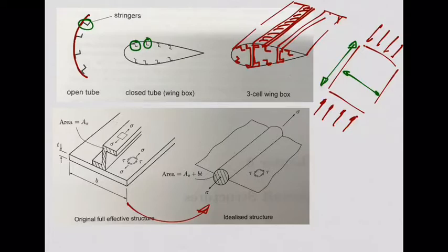Bending, you know, gives us direct stresses. Who is carrying the direct stresses? Well, that's why we have the booms here. The booms carry these direct stresses, sigma. Okay? So it's these two simplifications in geometry and in the stress states that will bring a huge difference to this analysis. Okay?